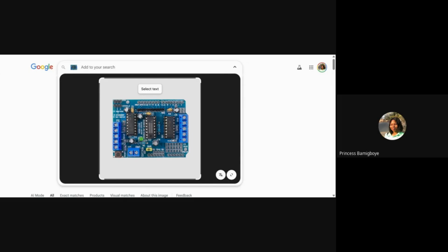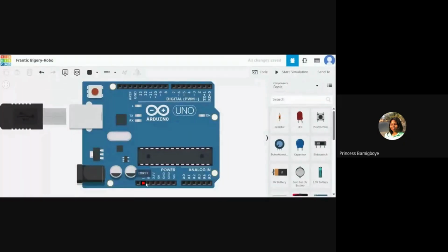And that is what this input output reference pin, this IO reference pin, does. It tells the shield that these are the range of values for voltage that this Arduino is working with, and that it gives off. For example, 5 volts. The Arduino is working with purely 5 volts voltage logic.